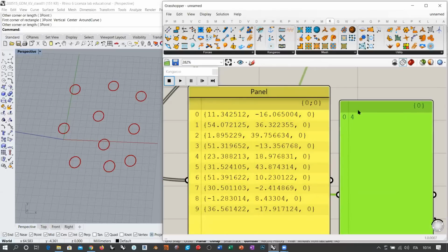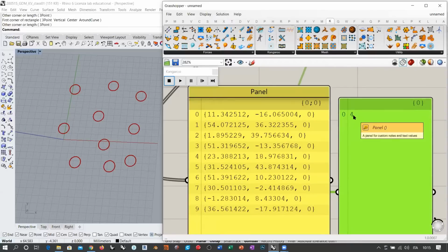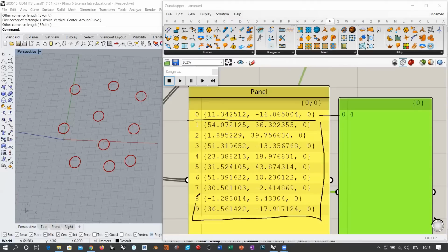It means that normally you will have the interaction between this point here and this radius, so you will have one circle. But then the longest list method says if you have more elements inside one list, you make the last element of the shortest list interact with all of them. So basically what happens here is that you have the first circle coming out from this one-to-one interaction. But then as there are more elements here, and you don't have any more elements in this list, the last element of the shortest list will also interact with all remaining elements of the longest list, okay? So this is what happens with the longest list method.